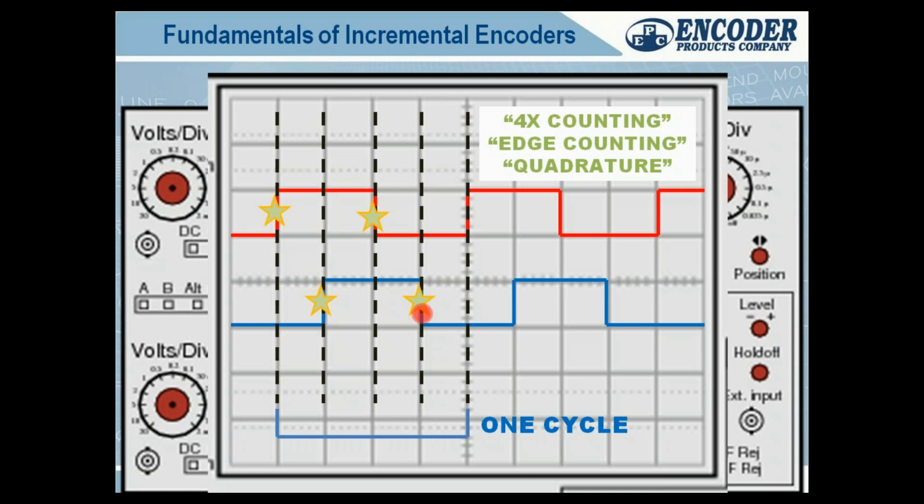Well, a lot of encoders have a maximum resolution capability. I run into a lot of vision systems where, you know, Jared, we really need 24,000 pulses per turn. And well, this encoder only goes to 10,000, but we can do something, multiply it by 4 and get you up where you need to be. Another reason to do this is, you know, Jared, I have a max frequency on this circuit. I can't go above a certain amount. And I say, well, let's get close to your max frequency, but do quadrature on your receiving end, and you can get 4 times that resolution without hitting the max frequency.